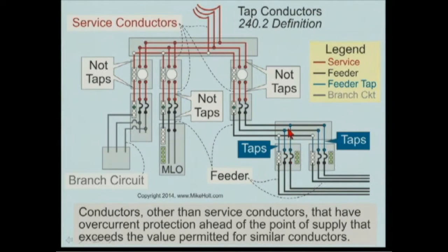This is a tap, and this is what I tell people. This gets kind of tricky. I tell people, look, you must provide overcurrent protection for conductors in accordance with 240.4. Either that, or you do one of two things. You're screwing up, or somehow you made what is called the law of compensating errors. You made enough mistakes that you actually got it to comply with a tap rule. So it's one of those two things. You're either going to make it comply with a tap rule, or you screwed up. Now watch how this works out.